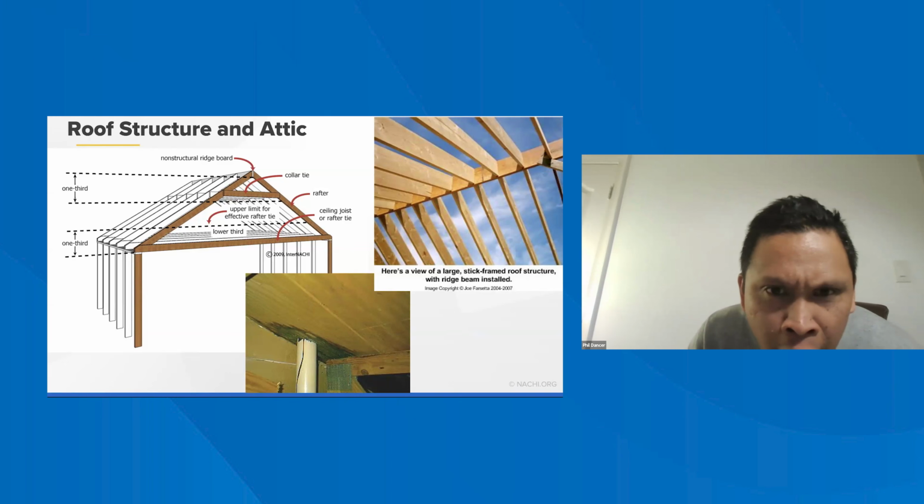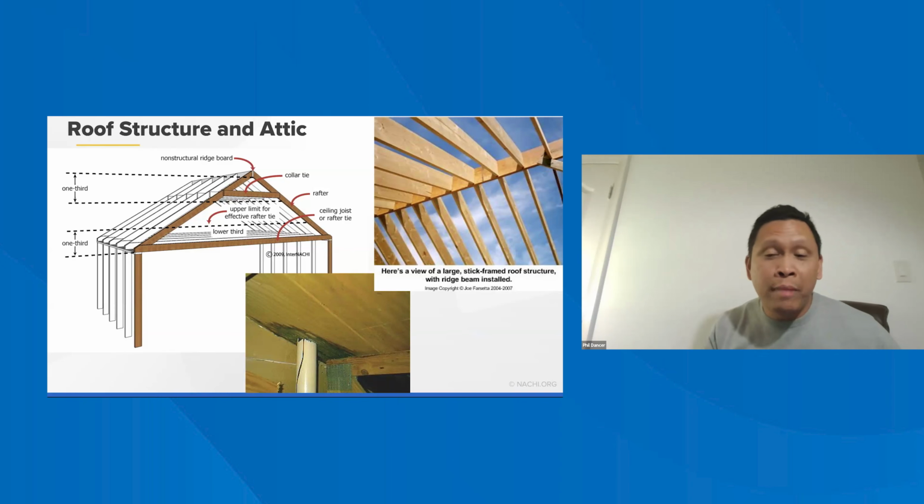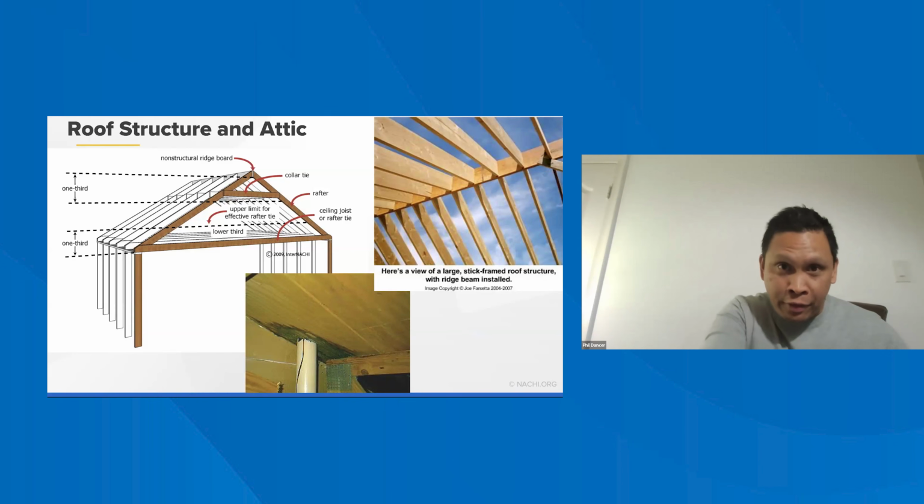I would put a double, but those are rafters. So if I were to build that home, I would probably be putting a double top plate on top. But also remember, the only way to know for sure if this needs a double top plate is to check the plan details of the builder to see if it's truly required.